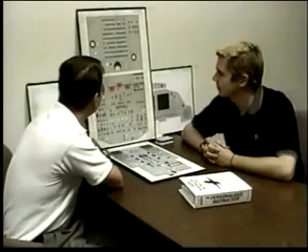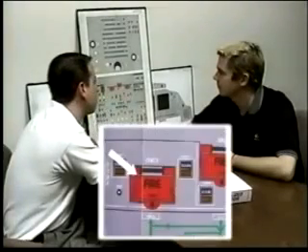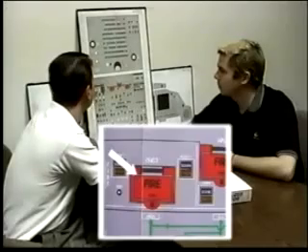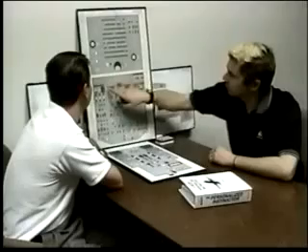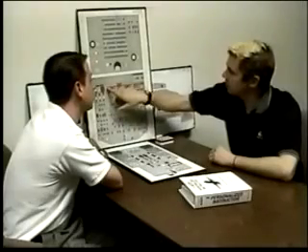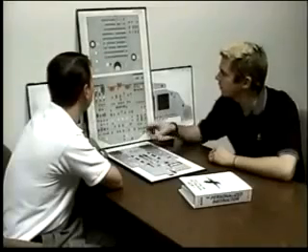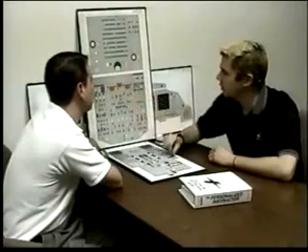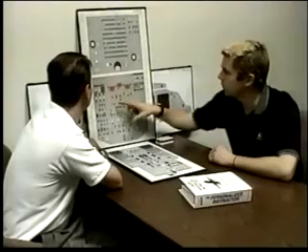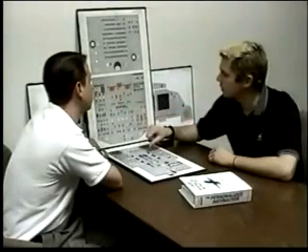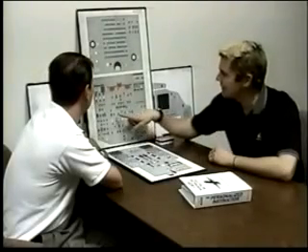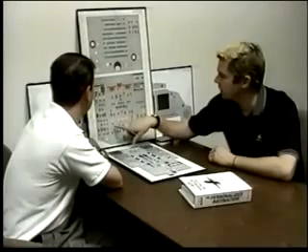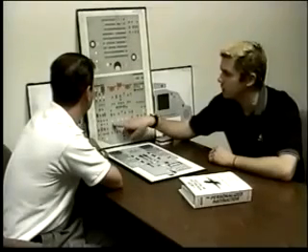Fire detection. Describe to me what occurs when you select an engine fire push button. When I release that fire push button, we have a little gouge we use, which is 21212. On the top, we start with 2. The 2 squibs are going to be armed, as well as the warning is going to be canceled. On the hydraulic panel, the hydraulic fire shutoff valve is closed. On the fuel panel, we've got 2 things. The low pressure fuel valve is closed, as well as the fuel return valve. On the electrical, we deactivate the generator, and then on the air conditioning, we close the engine bleed valve and the associated pack valve.